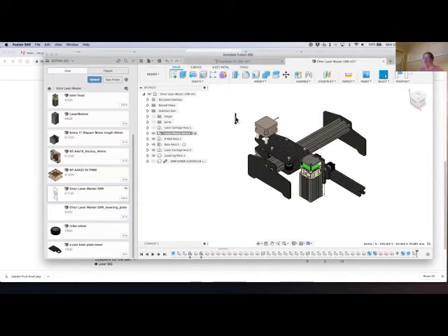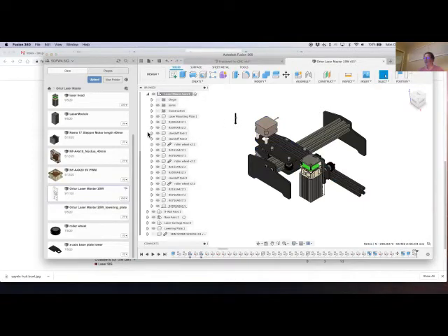So you see, now when I pick on this, the laser mount assembly shows a dashed, slanted line underneath it. And that means that I'm looking at something inside it. So when I open it up, there it is. It got added to the bottom of the laser mount assembly because it was activated, even though I pulled that out of a different assembly when I copied it.